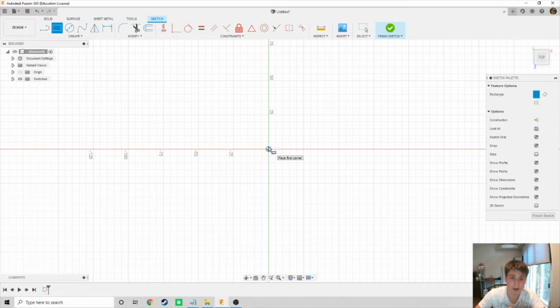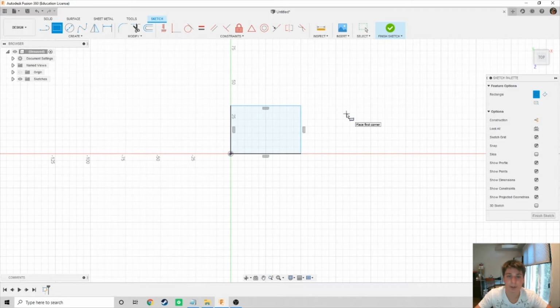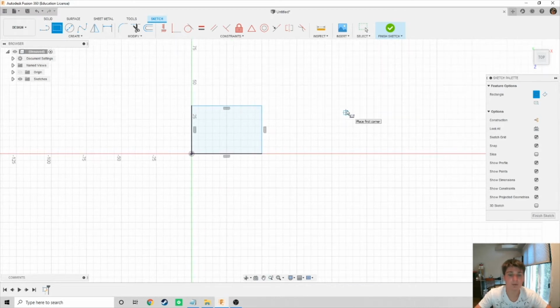I'm going to left click, and now I've started my drawing. Now when I move my mouse, I'm able to extend and draw the rectangle. On that second click, I'm going to finalize my drawing, and I'll know that it's a full shape when my interior coloring is blue. We'll get into open and closed shapes in a second, but the reason I like to call it a 2-3 click method is because, depending on what you're trying to draw, you're going to need more than 2 clicks.